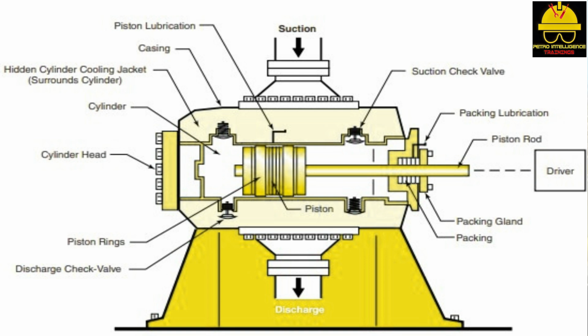Reciprocating piston compressor design varies from model to model. These variations usually occur in the total number of cylinders and in the arrangement of the suction and discharge lines. Most piston compressors have 1 to 4 cylinders. Each cylinder has its own piston, rings, and automatic valves. Common crankshafts can be shared with multiple connecting rods. The same cylinder can be equipped with multiple suction and discharge valves in double-acting compressors.